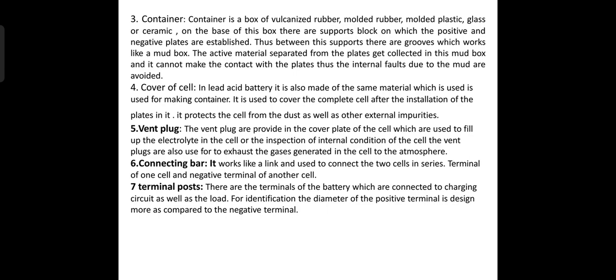The vent plugs are provided in the cover plate of the cell and are used to fill up the electrolyte in the cell or for inspection of the internal conditions of the cell. The vent plugs are also used to exhaust the gases generated in the cell to the atmosphere. Connecting bar: it works like a link and is used to connect two cells in series, the positive terminal of one cell and the negative terminal of another cell.